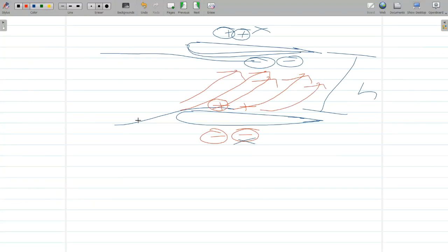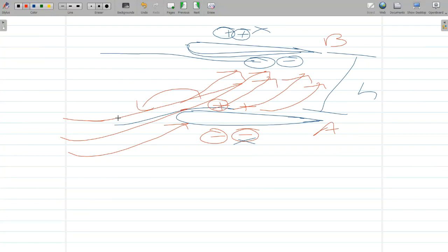So this basically will create an upwash, and that is true not only for airfoil B, but for airfoil A as well, because any free stream that is coming in will be taken up in this way. Since it is a subsonic flow field, whatever the flow field over here will influence something over here as well, and your free streams are essentially bent.